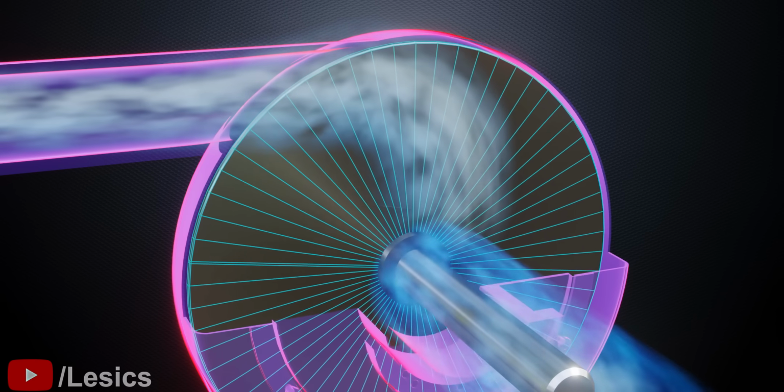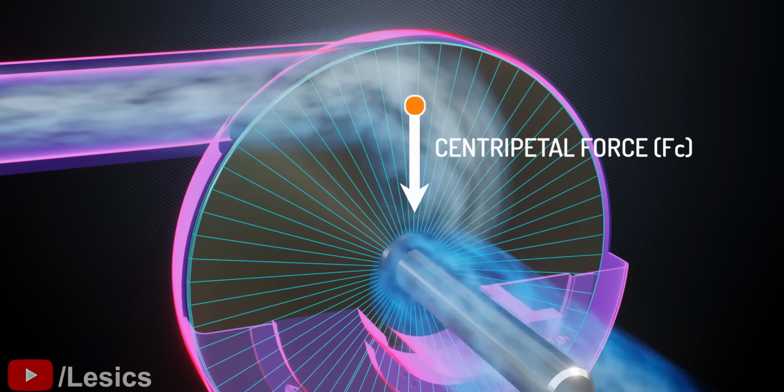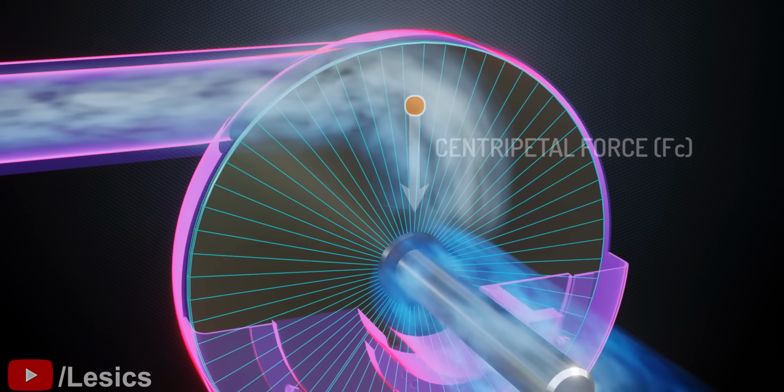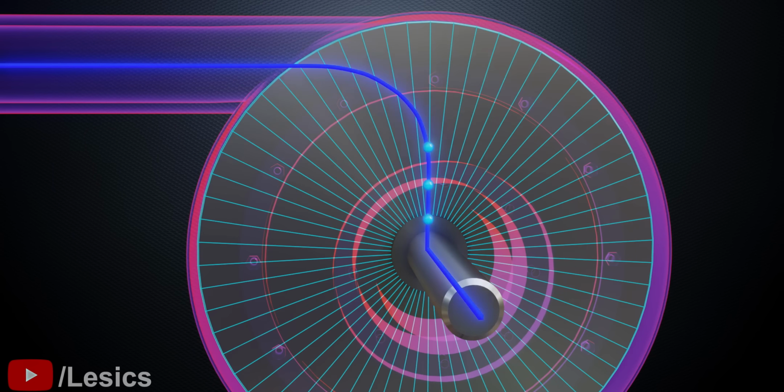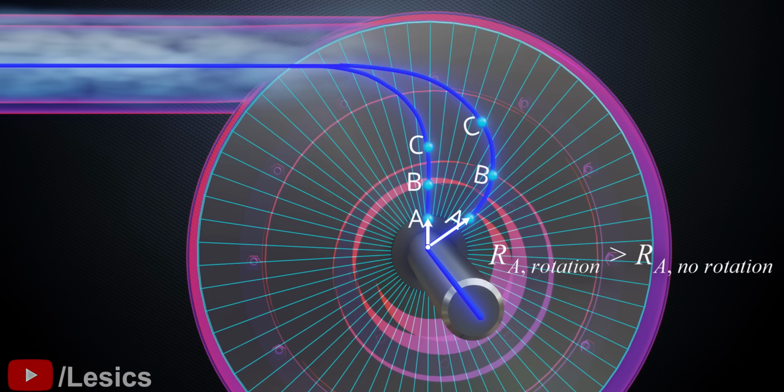When the fluid particles are rotating, they need a certain amount of centripetal force to maintain that motion. A fluid particle of the same velocity requires more centripetal force near the center than away from it. For this reason, the rotating fluid particles have a tendency to move away from the center. However, the turbine exit is at the center, so the fluid particles have to reach it eventually. Due to these opposing effects in the rotating case, the particle motion will curve out as shown. If you compare the radii of particle A in these two cases, clearly the curved path particles have more radius.